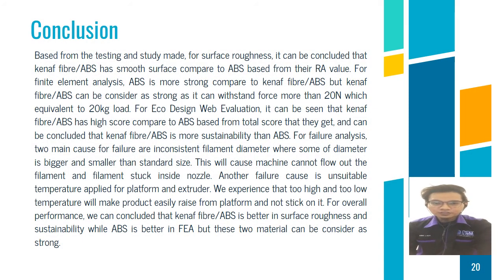Okay, for the conclusion, firstly I want to conclude from the testing that we have done. For the surface roughness, we can conclude that kenaf fiber ABS has a good surface finish compared to ABS.